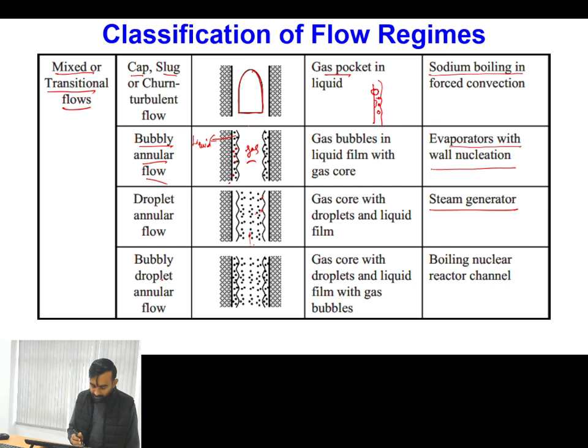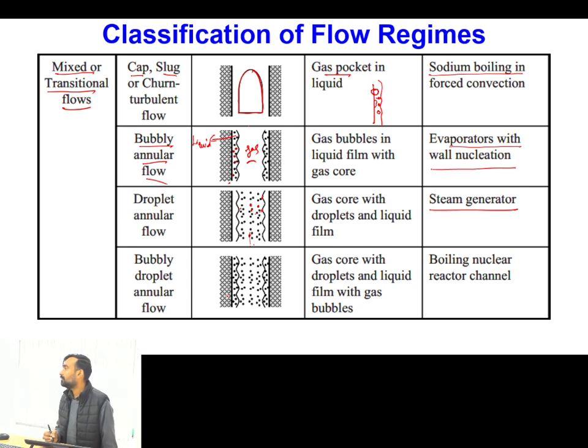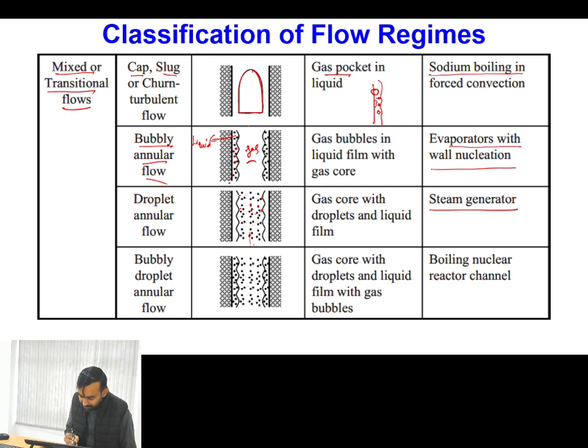Okay. Not in this droplet annular you are saying. So these are not bubbles. These are, yes, droplets. Liquid droplets are there. Your question is how these are coming? This is a wavy pattern. From this wavy pattern what will happen? If the wave is growing in amplitude, then it will form a lamella, and that fine lamella because of the gas shear will be splitting into small drops.